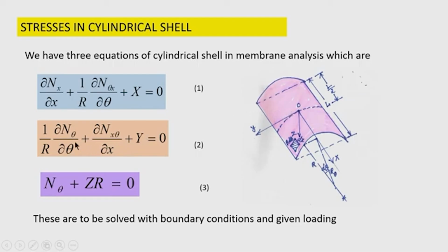The second equation is the equation of equilibrium in the y direction. Y direction is the direction along the tangent to the directrix. So, this second equation connects the membrane forces N theta and N x theta and the load in the y